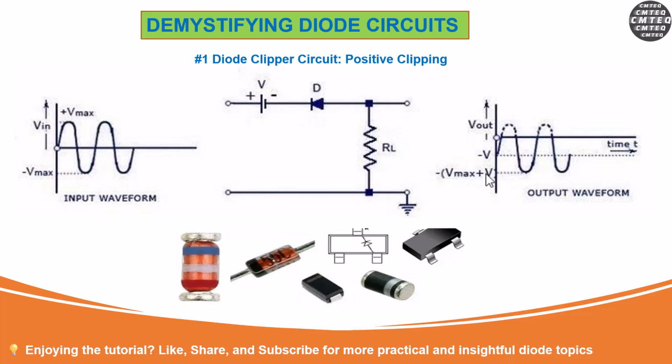But for a real diode, you have to subtract the drop across the diode, so that's going to be about 14.3 volt.